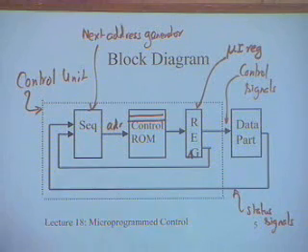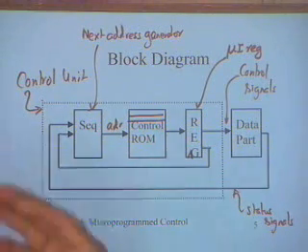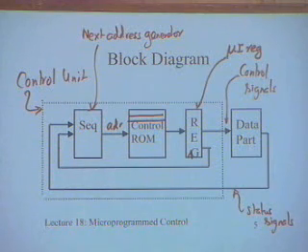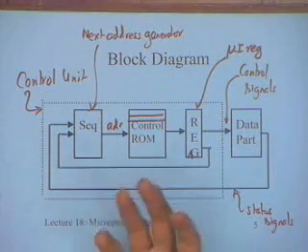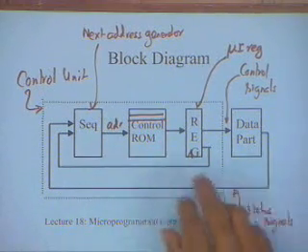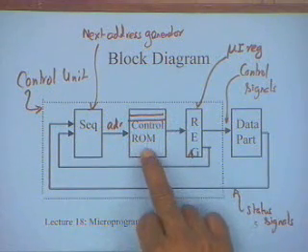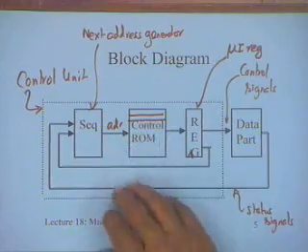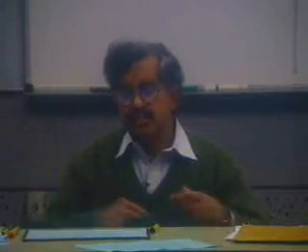So imagine if you have already wired it up, or actually done a VLSI design of it, the component has been designed, and you want to make another change, do all the simulation and so on, it's going to be extremely time consuming and expensive. Whereas in this situation, I may need to change only the contents of the ROM. Many changes can be accommodated by changing the contents of the ROM, but sometimes we will see that others may require a little bit more change.